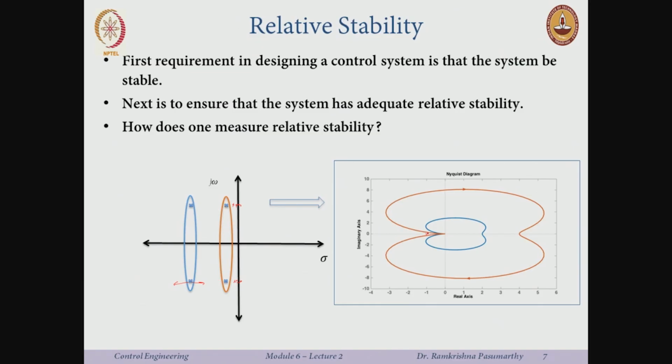Now let's come back here. What is the point of interest? As long as P equals 0, say the open loop system is stable, I just want Z to be 0, right? And if Z is 0, Nyquist tells me that the system is stable. Now who decides this? This is my guard, who says, well, you cross this line, you trespass, and you become unstable.